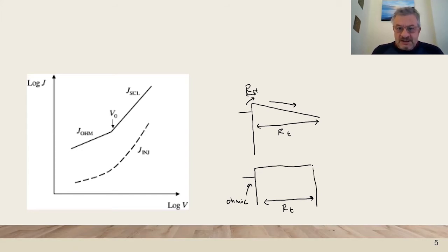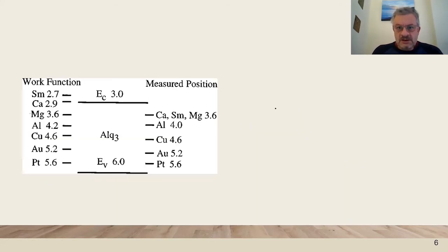So then we can check this quantity because a transport resistance in general must be proportional to the thickness. So if the total transport resistance is proportional to the thickness, then we are in a transport limited regime. Otherwise, if the device resistance is independent of the thickness, then it will be controlled by injection. And this we need to check experimentally.